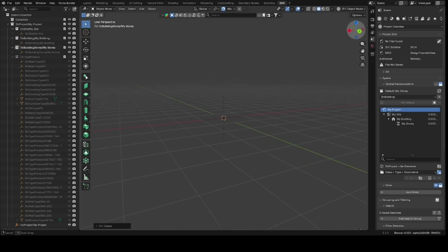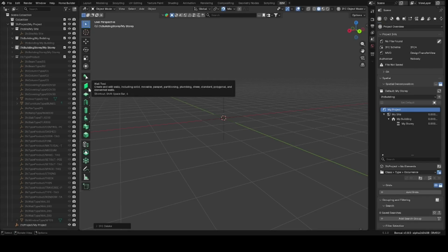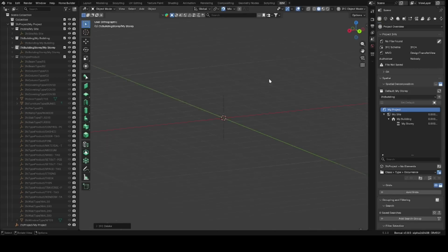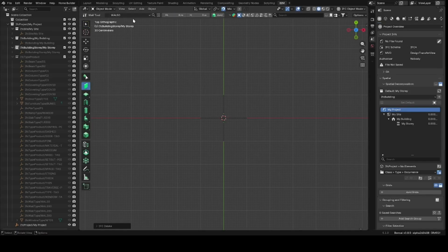Now another thing we're learning today is the different parts of this section, these tools you get here. For example, number one, you have the wall tool. The wall tool is mainly used to draw the walls when you're doing your drawings. For example, let me go to top view, which is number 7. I'm in my top view, so I want to use the wall tool.